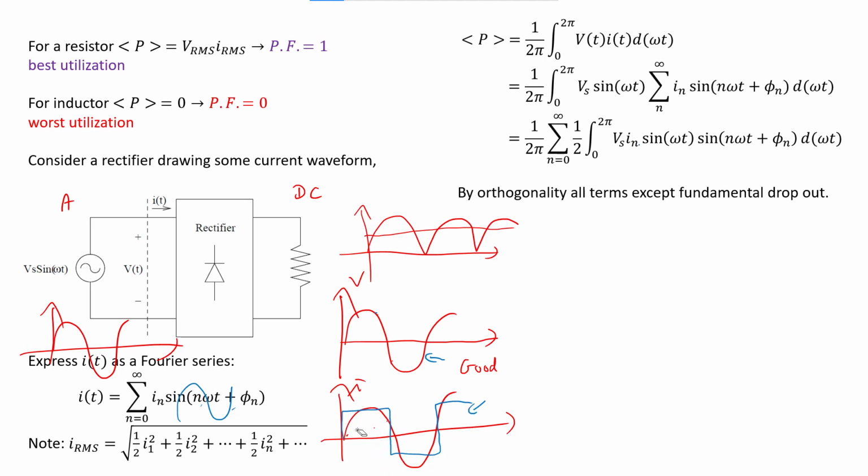So the square wave of current like this can be interpreted as the sum of all of these sine waves at different frequencies, and it can shape the form to be square as long as it's periodic. Only the first term, the pure sine wave like this one, contributes to the power factor.